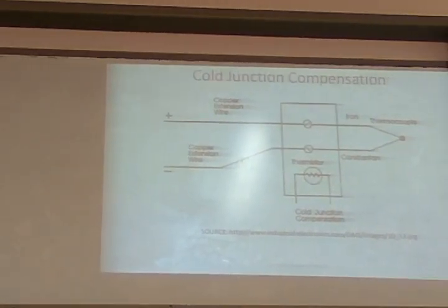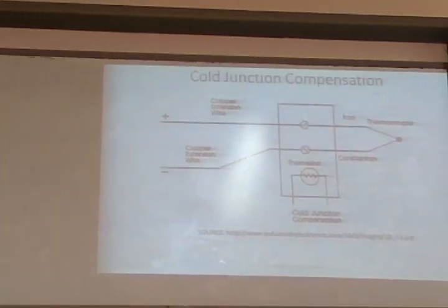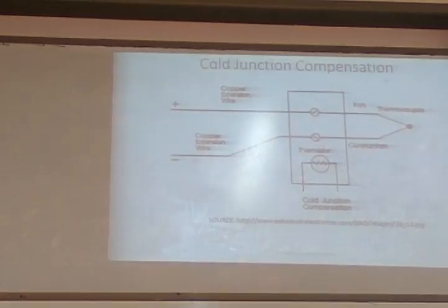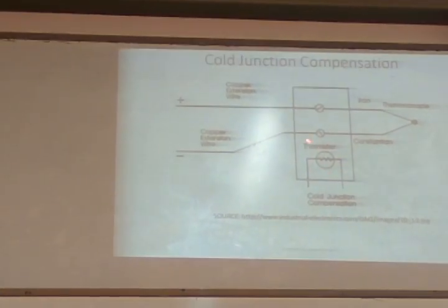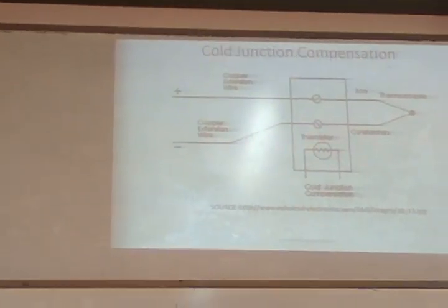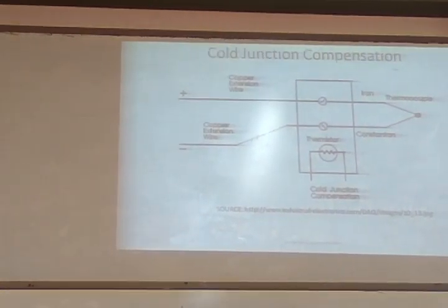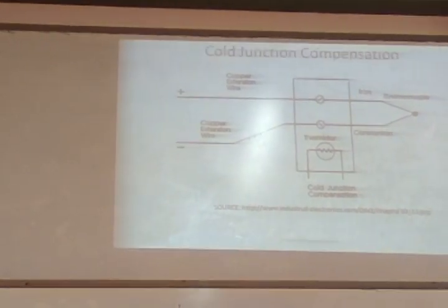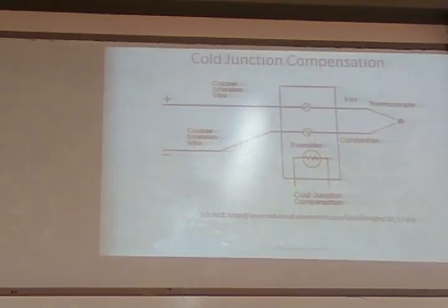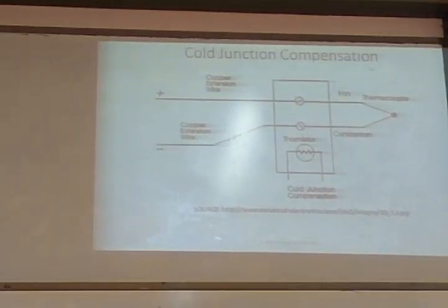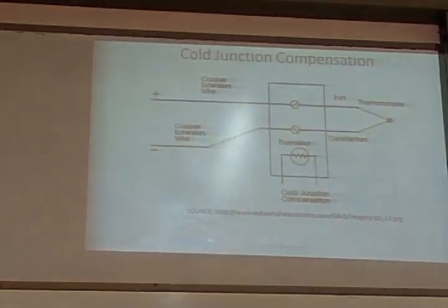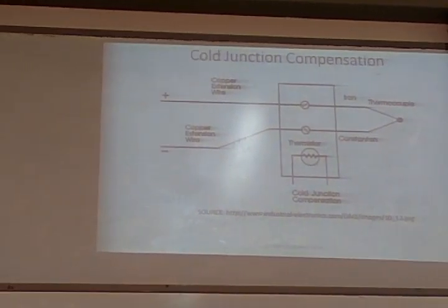You can ask me one question: sir, we wanted to measure temperature, that is why we use a thermocouple. Why do you use another temperature measuring device, an RTD, to measure the so-called cold junction? Directly use the RTD and measure the temperature. Why all this problem? An RTD can measure only from, let's say, some 0 degrees Celsius, or not even 0 degrees, some 20-30 degrees Celsius, to some 300 to 450 degrees Celsius, not more than that.